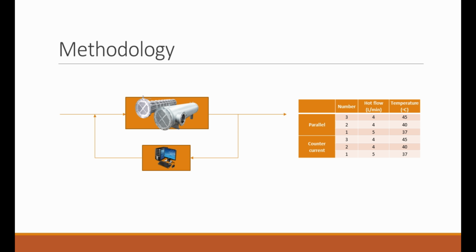In the experimentation of this project, the shell and tube heat exchanger was used, plus a computer program that controlled the flows of both hot and cold streams. Also, the flow for hot and cold fluids was set with their respective percentage of opening. This process continued until almost all temperatures stabilized, and the data taken in that period were stored in a spreadsheet. For each temperature and flow, 3 points were selected within the range of our group for parallel flow and counter-current flow. The following table shows the settings that the exchanger was used at.